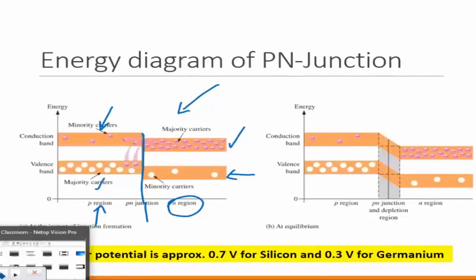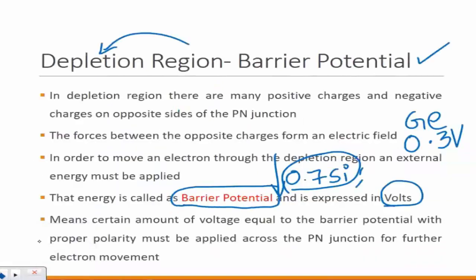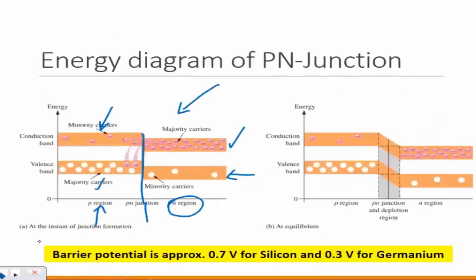So what makes this good is if it has more than 0.7 volts, it makes a circuit. If it doesn't have more than 0.7 volts, it won't complete the circuit. That is correct, ideally. But there may be a different way to put it together, because that 0.7 is under perfect conditions. Everything is good, everything PN junction is good. But how much current actually flows, that's another thing.